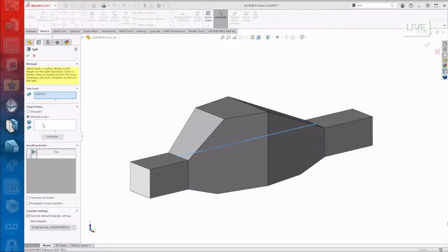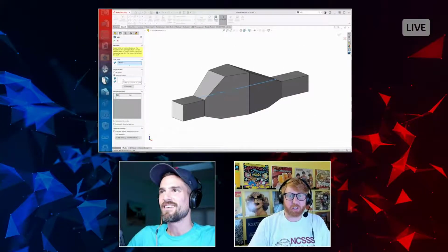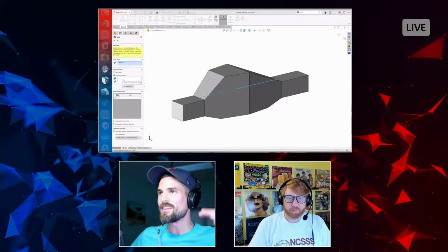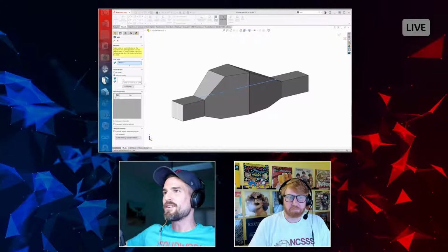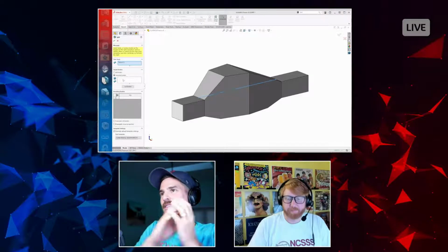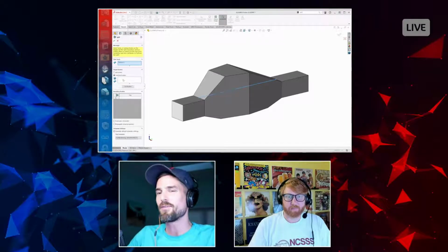Were you thinking that some people don't necessarily know you can do it with a 2D sketch? Or you might need to create a plane, a surface that extends past the boundaries of the model. No, because the sketch resides on a 2D plane. That 2D plane defines the direction the sketch would be projected, so that's enough information for us.